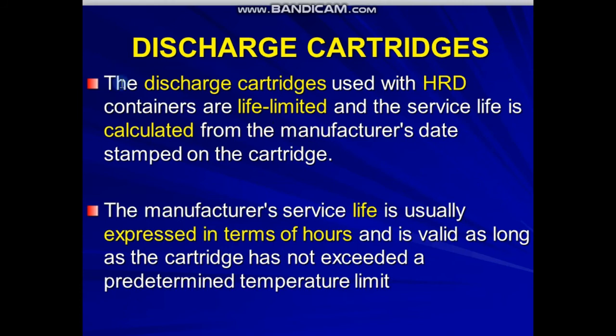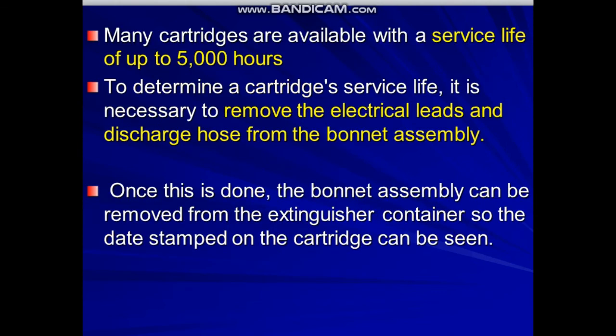Discharge cartridge. The discharge cartridges used with high rate discharge containers are life limited, and the service life is calculated from the manufacturer's date stamped on the cartridge. The manufacturer's service life is usually expressed in terms of hours and is valid as long as the cartridge has not exceeded a predetermined temperature limit. Many cartridges are valid for a service life of up to 5,000 hours.